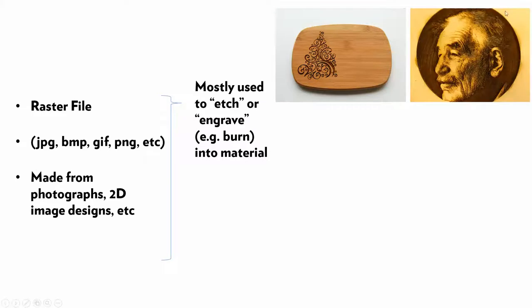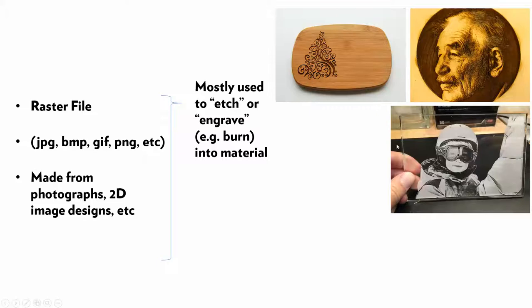Notice that as you're burning into plywood, the grain of the wood will also have an influence on the contrast. So you can see a bit of the grain of the wood in here. So you have to take that into account if you're trying to do a really intricate, detailed image. Otherwise, you might use something like glass or clear acrylic if you want a really clean, homogeneous substrate so that you don't have the grain of the wood to interfere with your pattern.